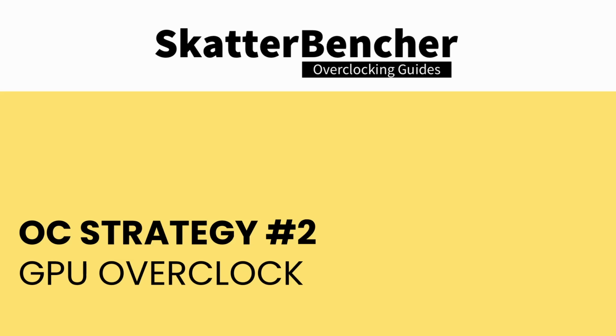While this tells us a more genuine story about iGPU performance and power consumption, it's not something that you would normally do. You wouldn't downclock your CPU cores to lower the iGPU power consumption. So therefore, for the rest of this guide, I will stick with the default CPU frequency. In our second overclocking strategy, we try to increase the graphics clock as high as possible. But before we get into that, let's first have a look at the clocking topology of a Ryzen 9000 CPU.